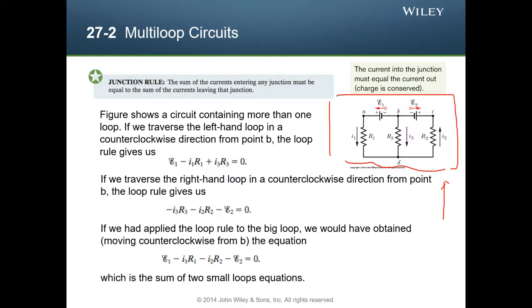So first of all, we can assume this one is V, this one is V, this one is V. For this current, maybe we can call it I1. I1 is nothing but V plus V1 over R1. So we write V plus V1 over R1. This is the first term. And for the second term, this is I2. I2 is nothing but V over R3.